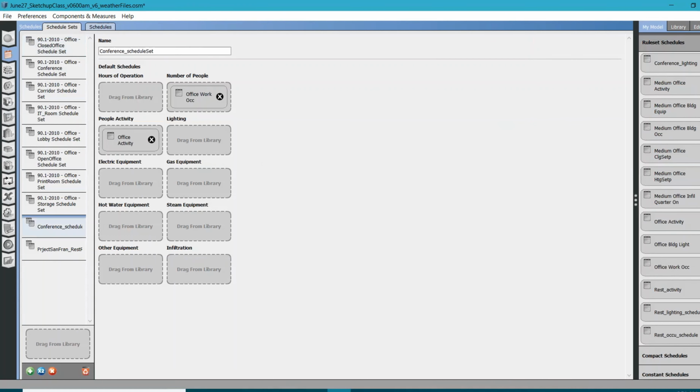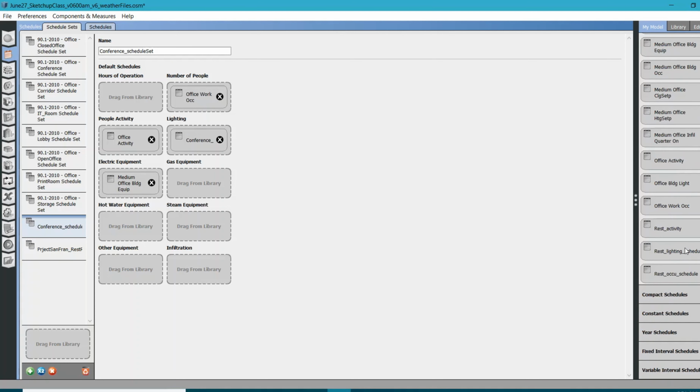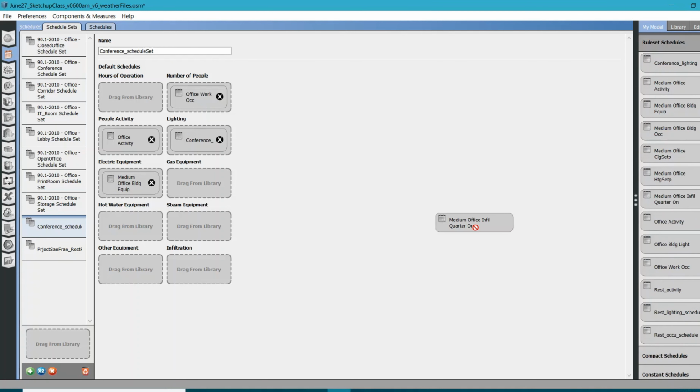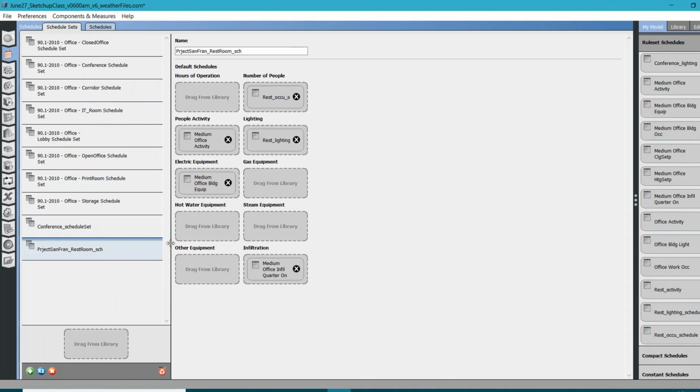Let me go back to my conference schedule set, drag and drop, and then I can use some existing ones for electric equipment and infiltration. What can I use for infiltration? Let me see. Oh, there's one infiltration here. Okay, so I have some information here. I can use this conference schedule set and assign it at the space type. Right now I haven't assigned this new schedule set to my space type, so it won't make any changes.